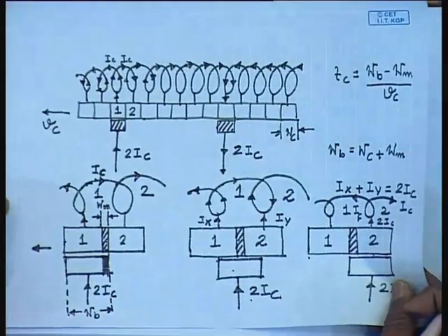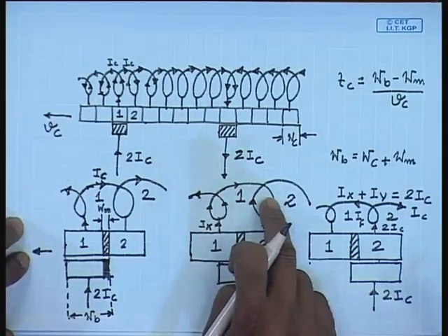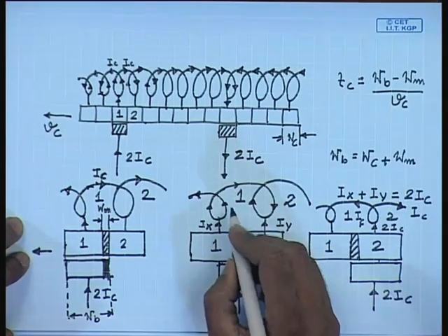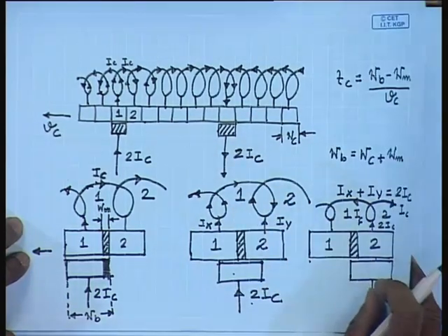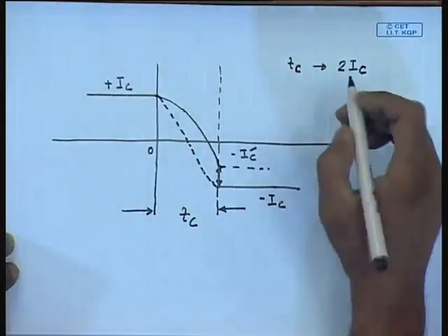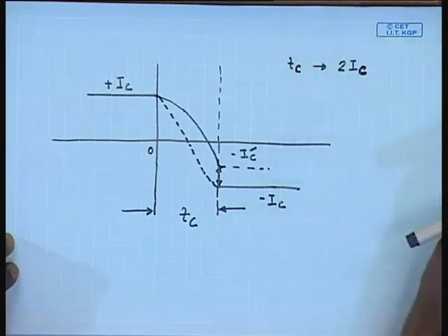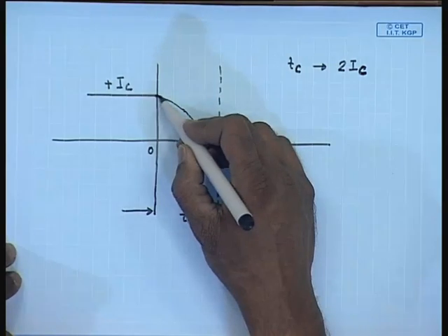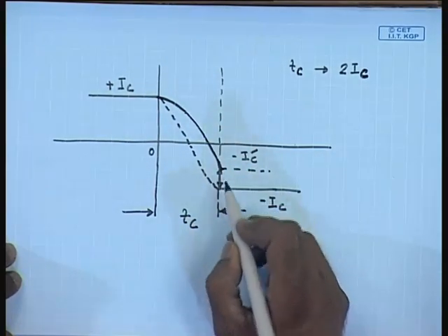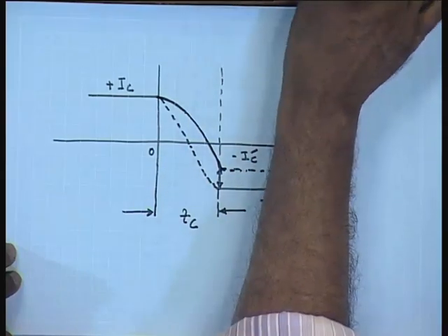Now, the coil undergoing commutation has some leakage inductance. This is mostly due to the overhang part of each coil. So, a coil will have a leakage inductance of Lc. This leakage inductance will delay the change in current in the coil undergoing commutation.